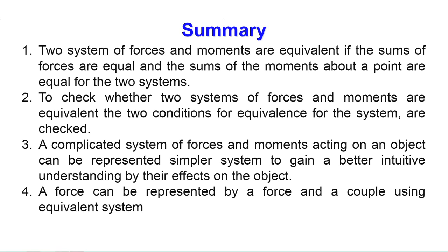So, today we have covered a few things. One is that two systems of forces and moments are equivalent if the sum of the forces are equal and the sum of the moments about a point are equal. To check whether two systems of forces and moments are equivalent, the two conditions for equivalence are checked. A complicated system of forces and moments acting on an object can be represented by a simpler system to gain a better intuitive understanding of their effects on the object.